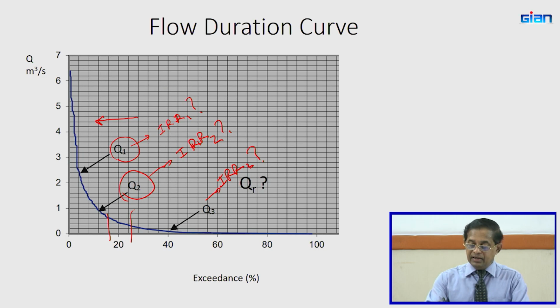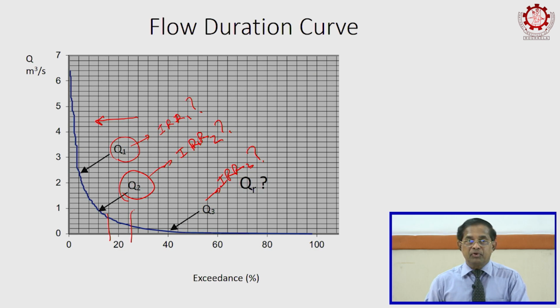Ideally the rated flow should be decided by financial consideration, which project brings the higher return on investment. In Sri Lankan condition, we know it is somewhere here because of the tariff paid in Sri Lanka, but I can't recommend that for you. You must find out from the flow duration curve what is applicable for you, depending upon the return on investment after doing a cash flow analysis, which a financial expert or accountant can do.